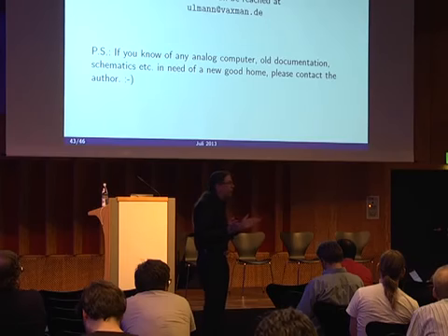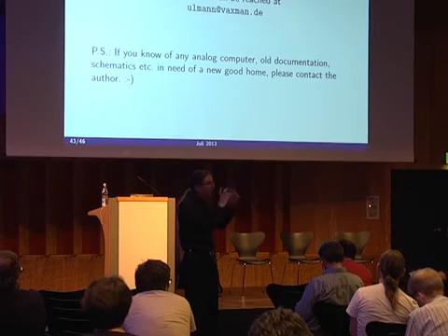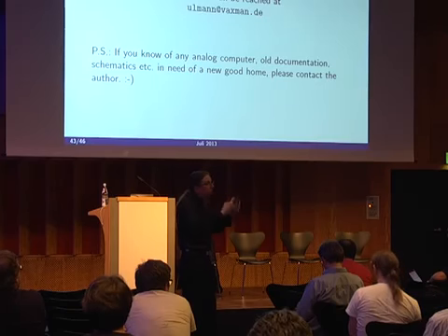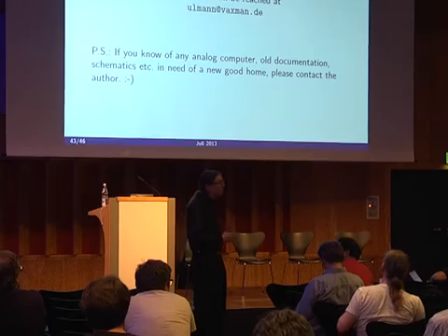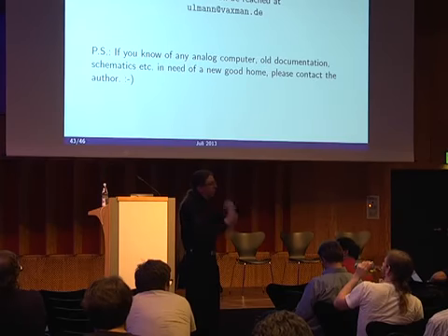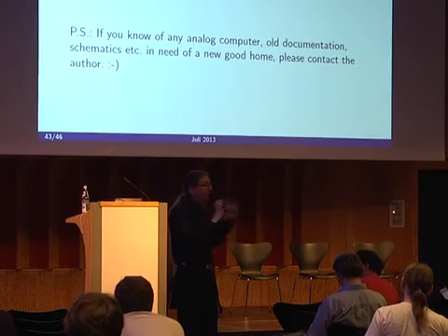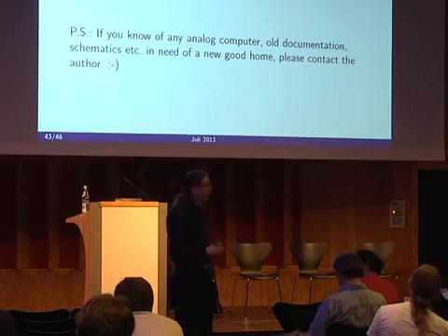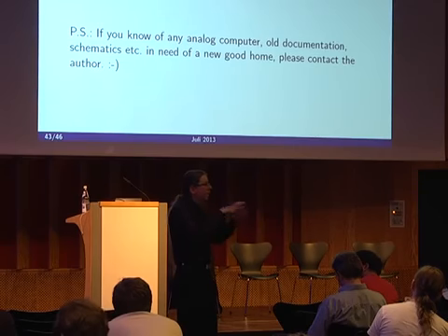A modern implementation could look like an FPGA with multiplexers interconnecting some macro blocks containing the integrators and various computing elements, and you would change the structure by just feeding the multiplexers with the correct bit patterns for selecting the proper input lines and routing signals to the proper output lines. A traditional analog computer really changes its structure while I, as a programmer, plug in all the plugs. But a modern implementation has, of course, a fixed design, but uses multiplexers to change the interconnection of the various computing elements.